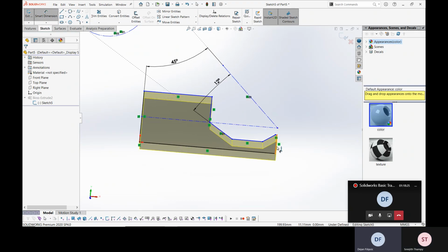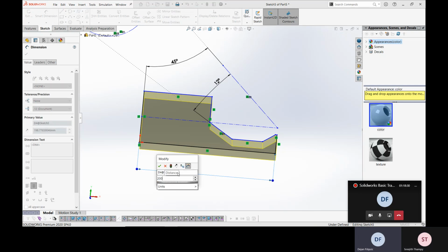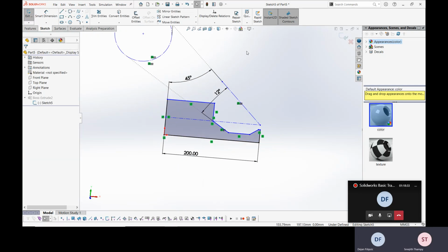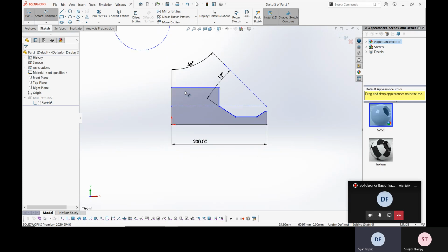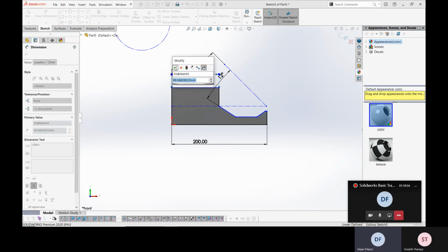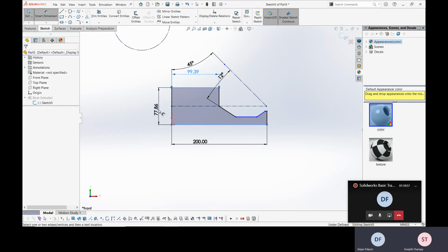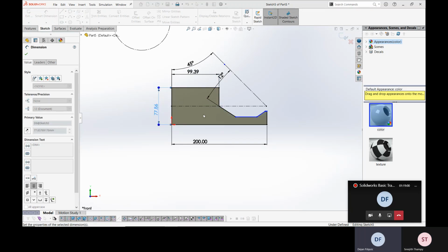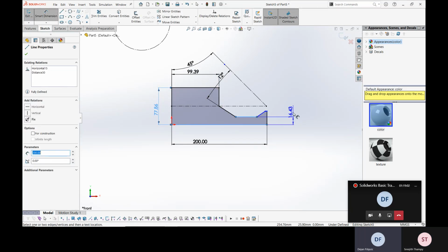Yeah, it's going to be a routine when they start using it, but just know what the capability is. So when you do a brand new object, you are doing it on a white canvas, right? But when you do an object in an assembly that links to other objects, you can reuse all the features of a part next to it in your sketcher, right? So when you sketch and you have a part underneath, you can connect lines, dimensions, and everything to the part underneath. So it's really a lot easier when you can consume all of that information in the sketch.